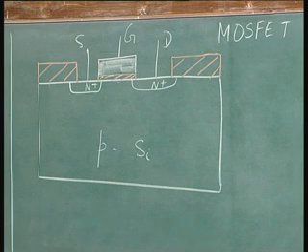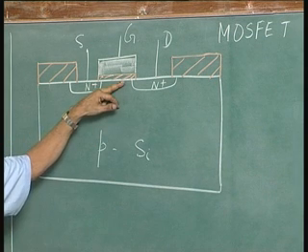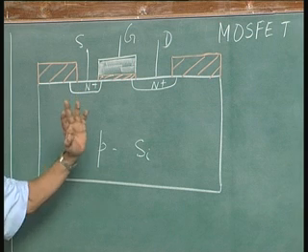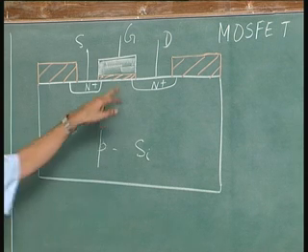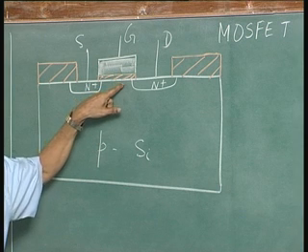What is an ideal insulator? Zero charge within that, and a very clean interface. There are no charges staying at the interface, that sort of thing. So, when we say due to the problems related to native oxide of gallium arsenide and phosphide, the problem is related to this property of the oxide and the interface.